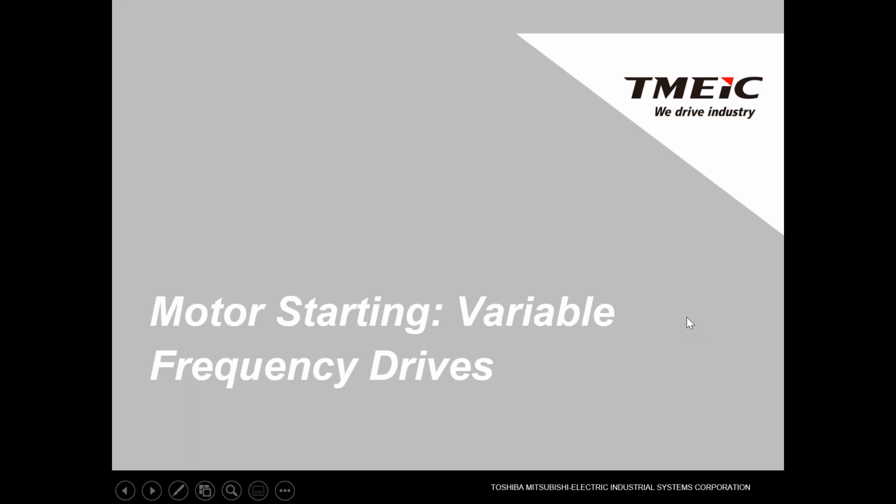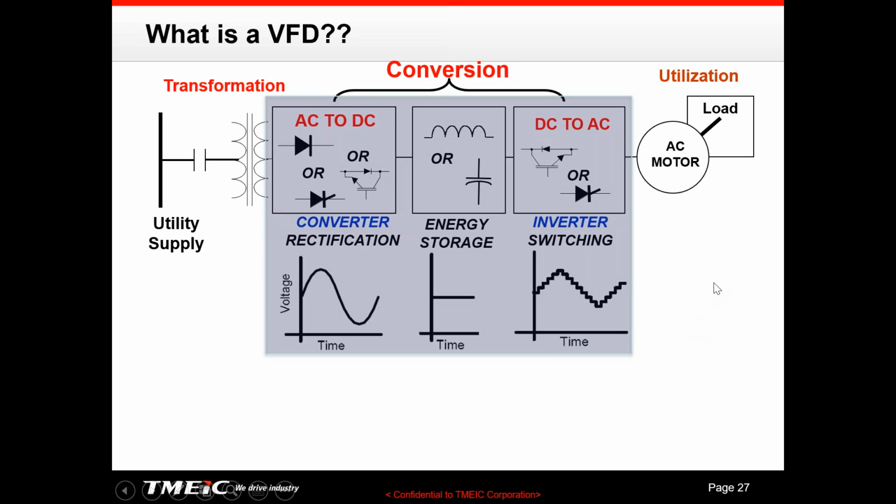Okay, now we want to talk about the variable frequency drives starting method. I'm not a VFD expert, but my understanding is the VFD is the power conversion equipment. Any VFD consists of these three components here. The first is the converter section, where you convert the AC to DC using diodes or IGBTs, which are the power semiconductors, right?